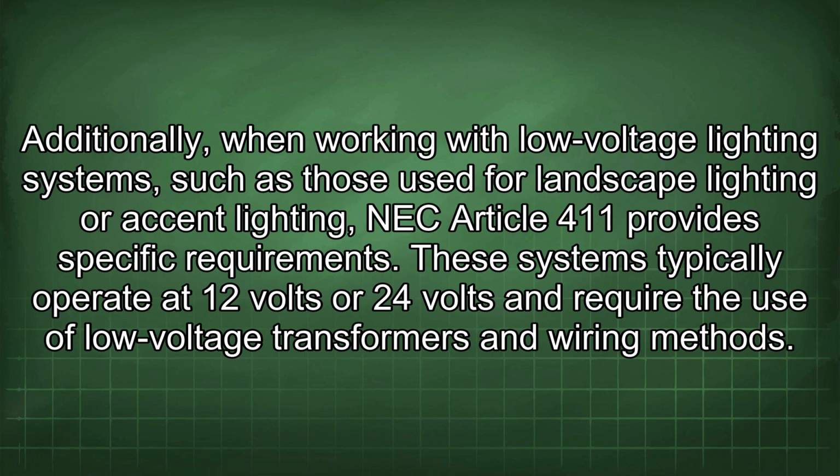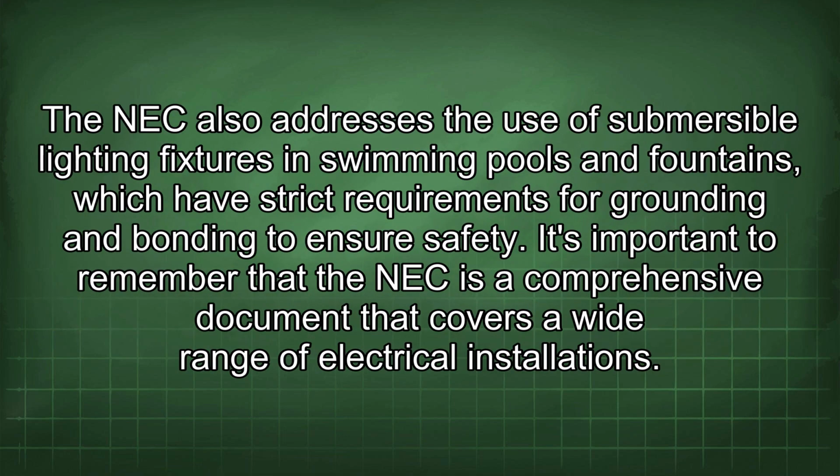Additionally, when working with low-voltage lighting systems, such as those used for landscape lighting or accent lighting, NEC Article 411 provides specific requirements. These systems typically operate at 12 volts or 24 volts and require the use of low-voltage transformers and wiring methods. The NEC also addresses the use of submersible lighting fixtures in swimming pools and fountains, which have strict requirements for grounding and bonding to ensure safety.